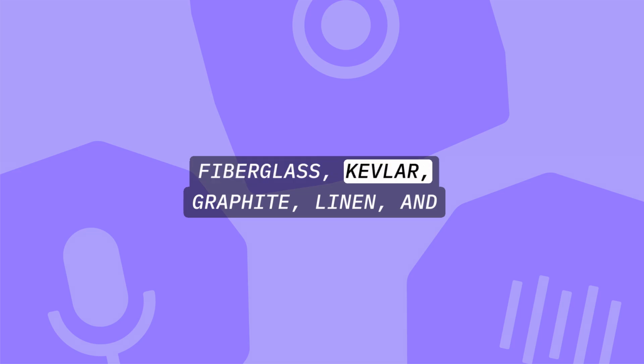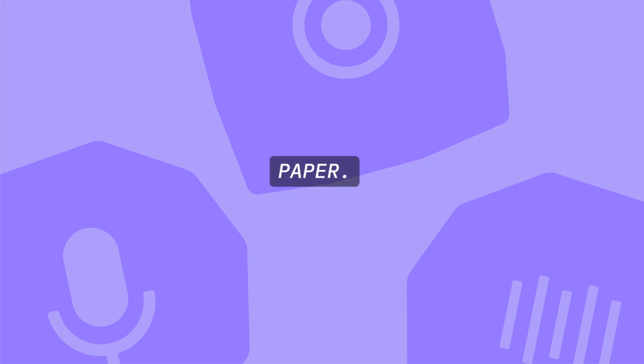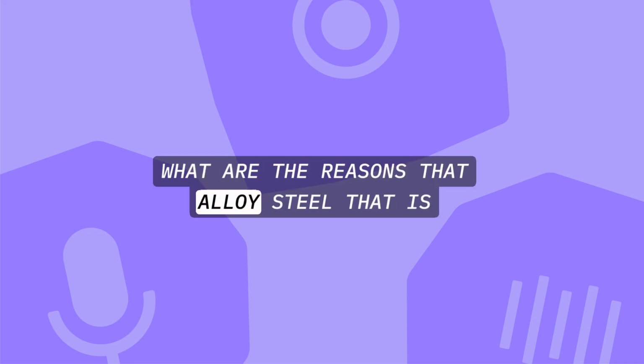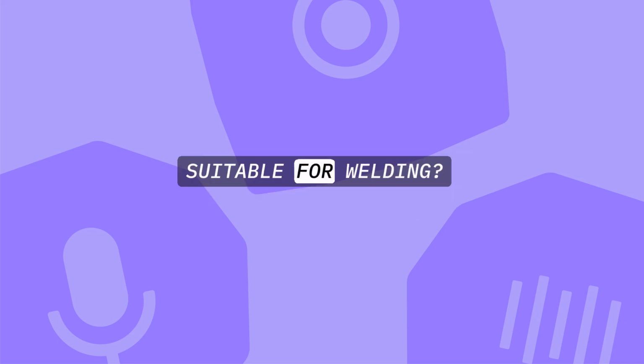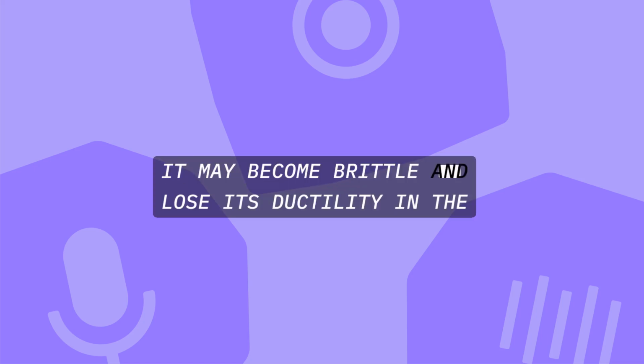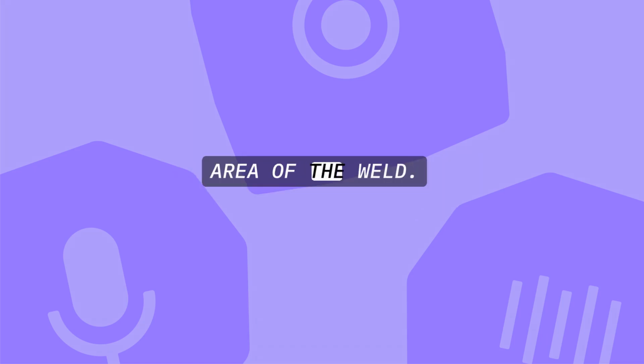Fiberglass, Kevlar, graphite, linen, and paper. What are the reasons that alloy steel that is responsive to heat treatment is usually less suitable for welding? It may become brittle and lose its ductility in the area of the weld.